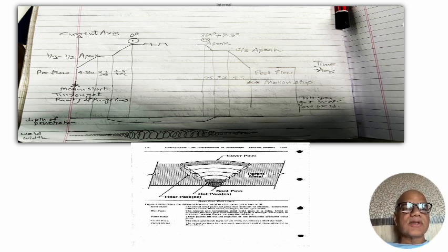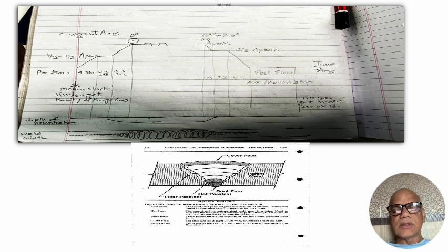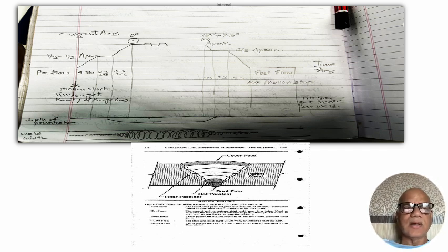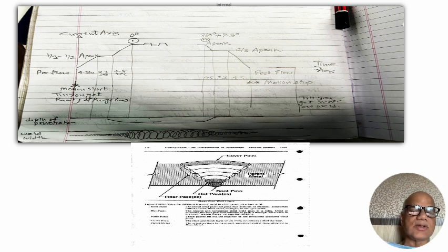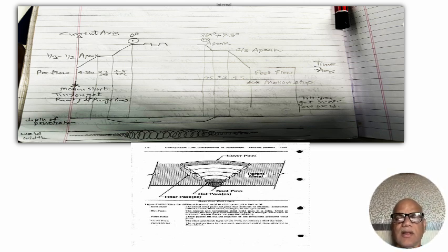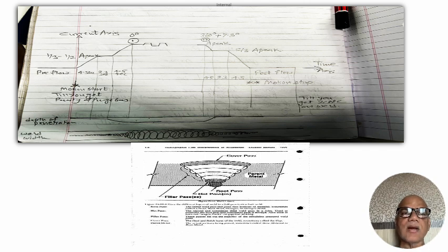And then after stabilizing for another 2-3 seconds, you start the second upslope, which is going to take us to the final current. As we saw in the earlier slide, either we start pulsing right from the zero current itself, or we will start pulsing once we reach the final value, and then the pulsing continues to the required rotation. And this is the point where, for a circular seam, our 0 point starts.